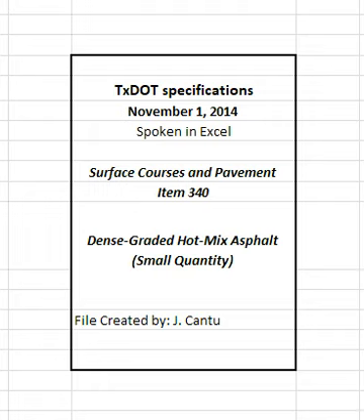The engineer will use the department's mix design template, when electing to verify conformance, to calculate the percent of Class A aggregate retained on the number 4 sieve by inputting the bin percentages shown from readouts in the control room at the time of production and stockpile gradations measured at the time of production. The engineer may determine the gradations based on either washed or dry sieve analysis from samples obtained from individual aggregate cold feed bins or aggregate stockpiles. The engineer may perform spot checks using the gradations supplied by the contractor on the mixture design report as an input for the template. However, a failing spot check will require confirmation with a stockpile gradation determined by the engineer.